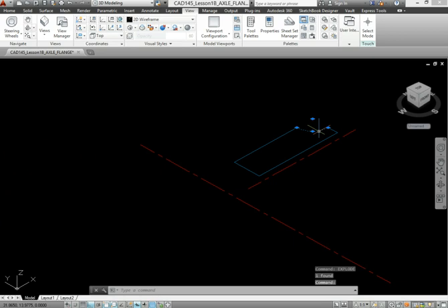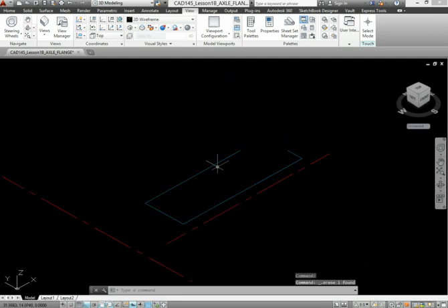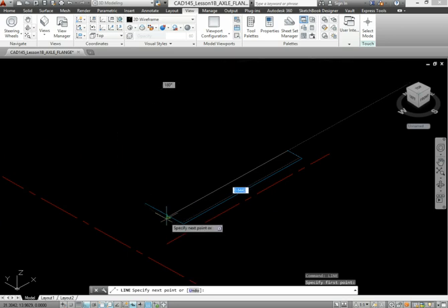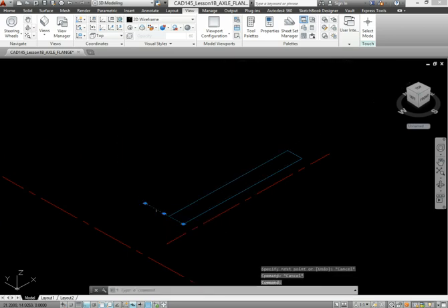Use the explode command. Now this is its individual parts. I typed in explode. Let me erase that. But we do need that. We don't need this. Type in draw a line from here to perpendicular. Trim this off. Okay. Use the region command. Select these 4 objects to turn these 4 separate lines into a region. Hit enter. Your axis is going to be, hit enter. The region command is finished. We now have a part.